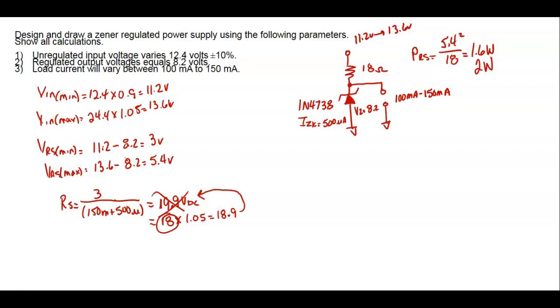So now we've got our size. Now we've got everything we need to know about that resistor: 18 ohms. We know it doesn't matter now whether it's 5% high or 5% low. We know that, and we chose the right wattage rating. Right? Everybody okay? Yeah, but the way it's set up, I'm not asking you for what size. I'm just asking for that answer right there. I'm not asking you right now to actually choose the wattage rating, but you can see how it goes, right?